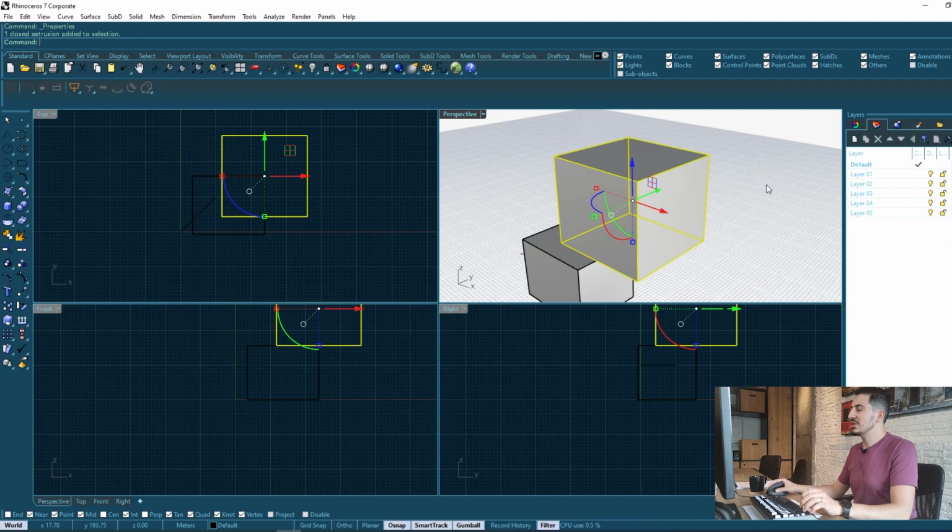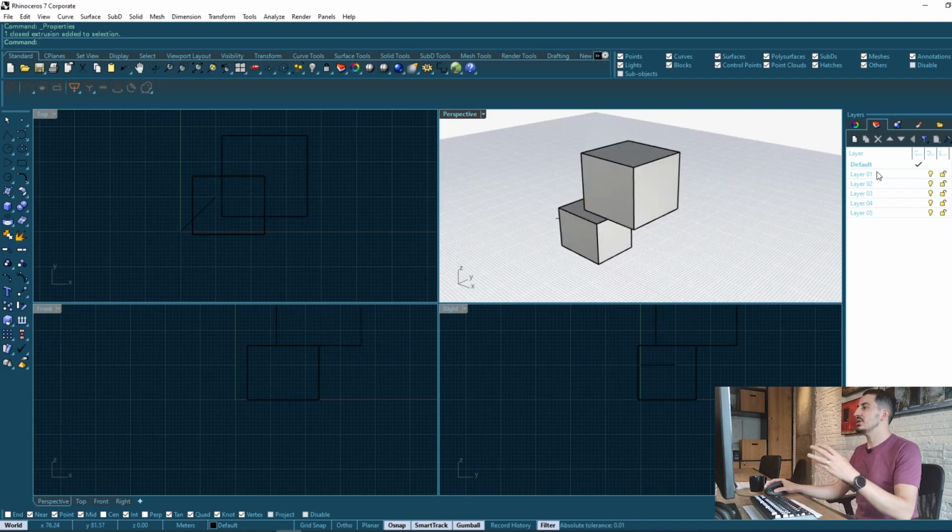The next one is a very handy, very useful thing that we use, as you know, in AutoCAD or in Rhino or similar programs, which is the layers. So in what layer do you create your objects? This is a very helpful panel to organize your work, to put different objects in different layers. So if you're planning a 2D plan, you put the doors in a door layer, you put the windows in a window layer, and the walls, and this way you can organize your work.